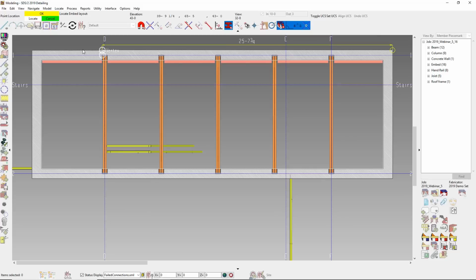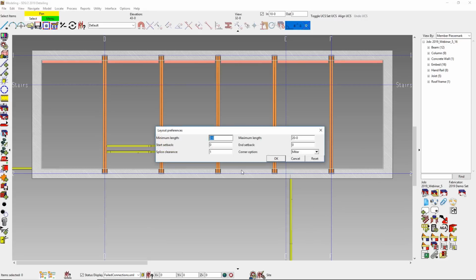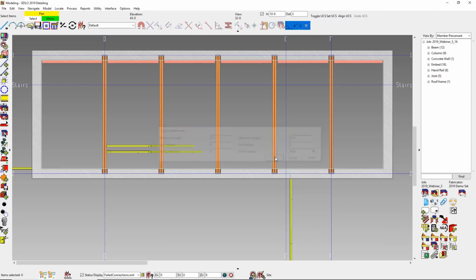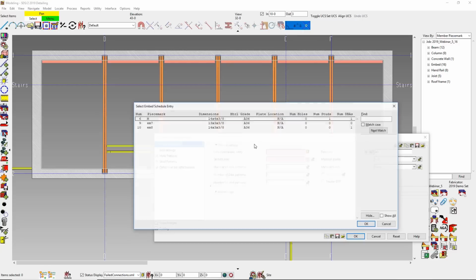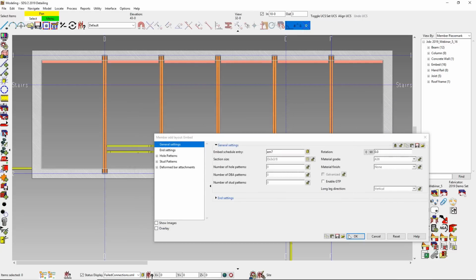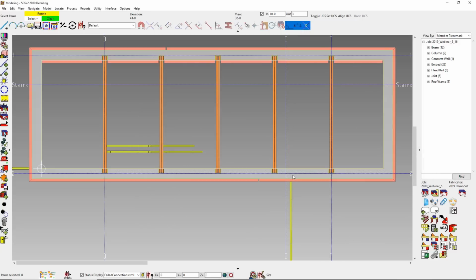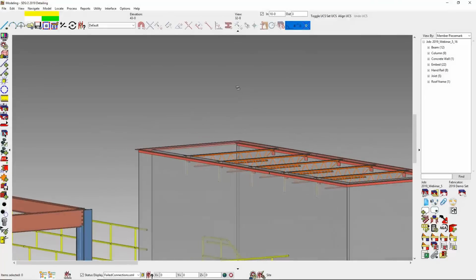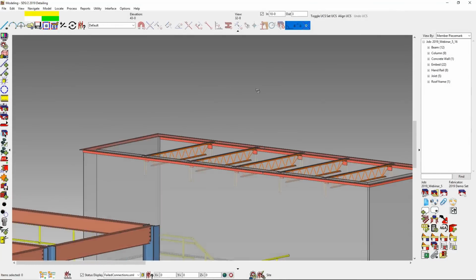This is also going to cut down on my construction time since we'll have accurate quantities and everything's going to fit properly. Then I could send out this LOD 400 model with all of the material and my secondary steel included. Then the other trades involved on the project can plan their work packages based off the model that I've provided. So therefore everything's going to be accurate.